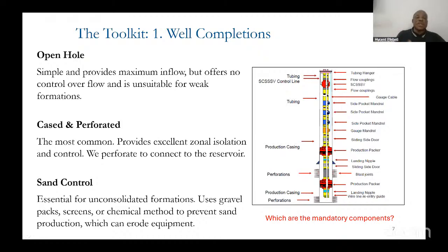That gives us maximum inflow because a large portion of the sand face is exposed to the wellbore. But we cannot do that in an unconsolidated formation. Then we also have cased and perforated.